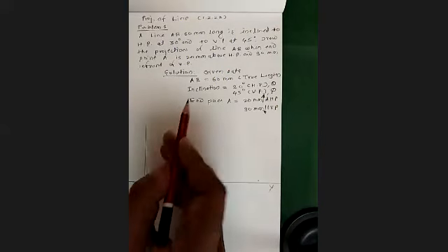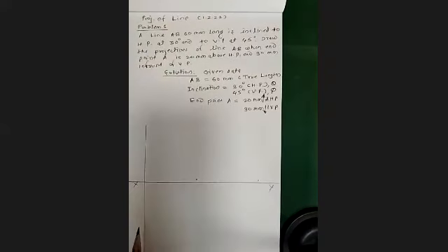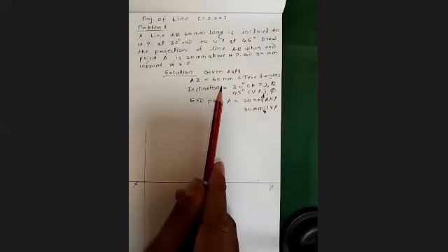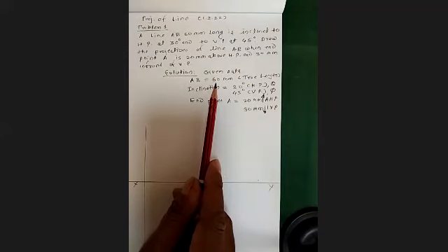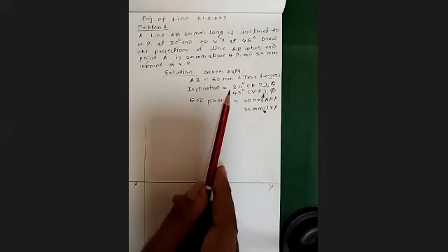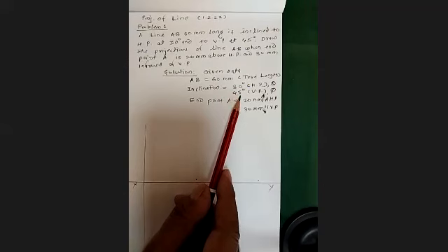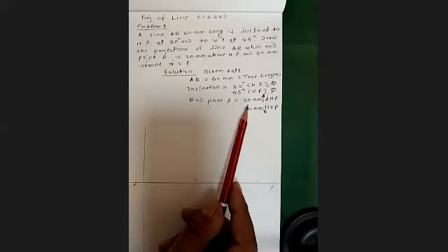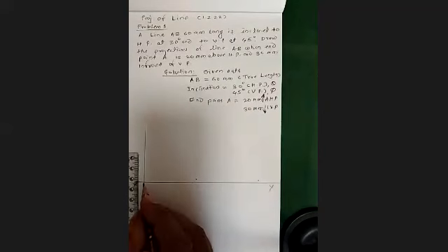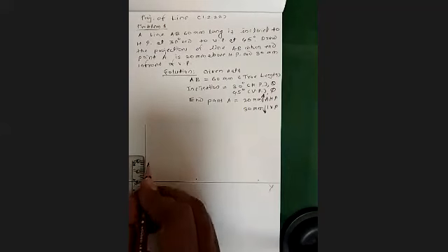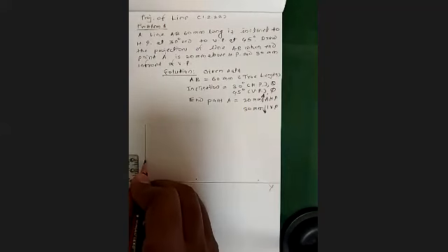Another line. Okay. Then you have this much data with you. So you have to think, can you take 60 millimeter as a first data? No, we can't take it. Even 30 degree, 35 degree, 45 degree, no. But endpoint A we can mark easily. So from here at 20 millimeter above HP, we'll take 20. So this will be the point above.